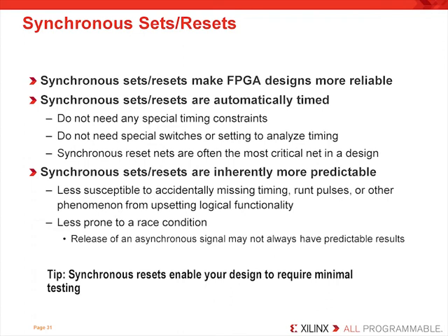Inherently, synchronous resets are much more predictable. Synchronous resets are less susceptible to accidentally missing timing and, of course, race conditions. But the bottom line is that chances are that if you use synchronous resets, your design will have a much greater chance of working right out of the box. This is dependent on the timing analyzer verifying that you are meeting timing and your functional simulation working properly, of course. With asynchronous resets, there is much less uncertainty because there are a lot of things that can go unnoticed because asynchronous sets and resets are not covered by a period constraint and require special path-specific timing constraints to be applied to your design.